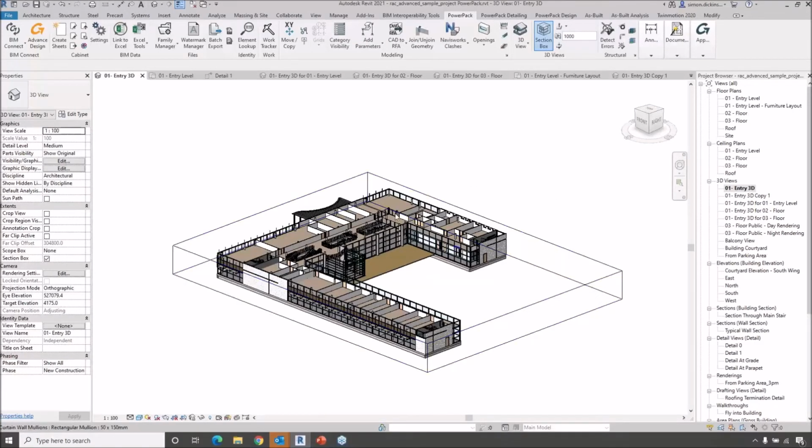It might be that I want to look at one of the other planes, so let's switch that to the X. Now when I move that, you can see that the X plane is moving down. Each click of the wheel is going to allow me to move it 1 meter, and I can start to do these 1 meter increments through. So it's very nice, easy control over that.